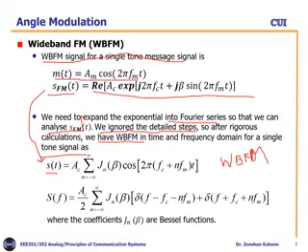So s(t) equals, in terms of Bessel function, Ac summation n equals minus infinity to plus infinity, and these are the Bessel amplitude coefficients, Jn(beta). So n ranges from minus infinity to infinity, and beta, you know, is the modulation index.